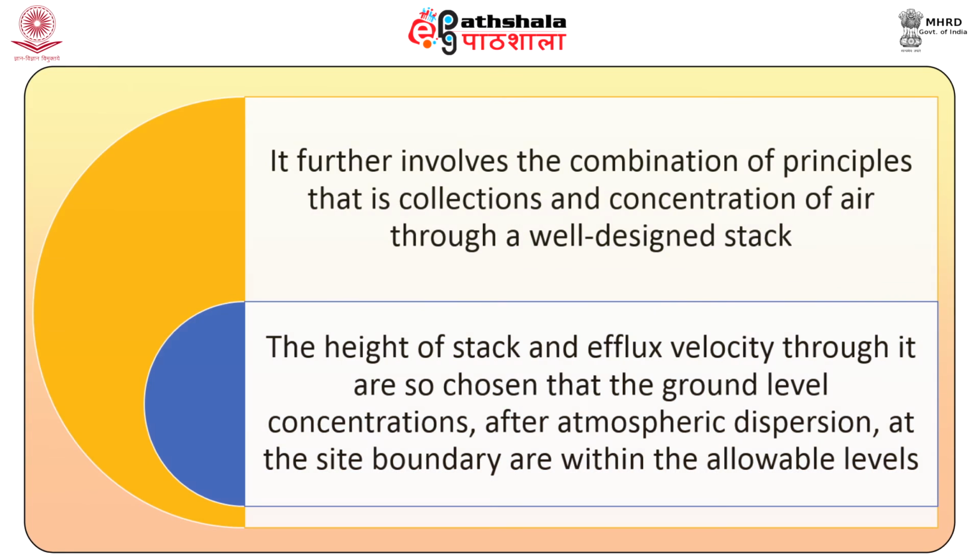It further involves the combination of principles, that is, collection and concentration of air through a well-designed stack. The height of the stack and efflux velocity through it are so chosen that the ground level concentrations after atmospheric dispersion at the site boundary are within the allowable levels.